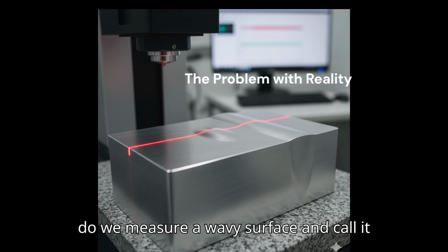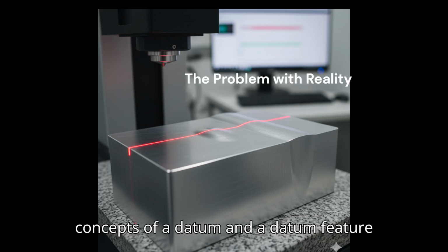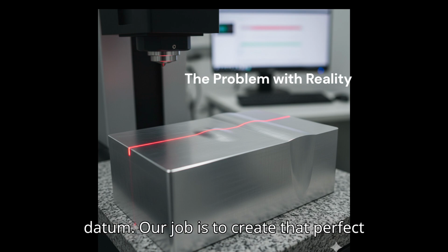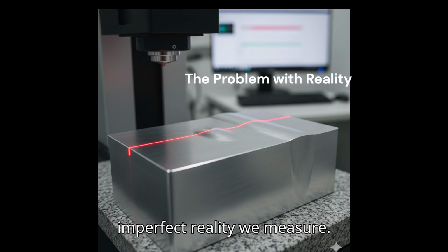So how do we measure a wavy surface and call it a single perfect plane? This is where the concepts of a datum and a datum feature come in. The physical imperfect surface is the datum feature, and the perfect theoretical plane we measure from is called the datum. Our job is to create that perfect plane in the virtual world based on the imperfect reality we measure.